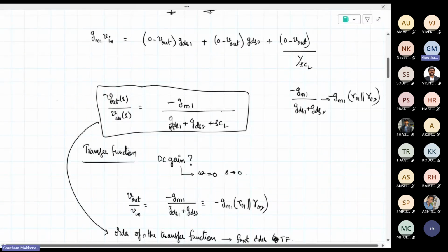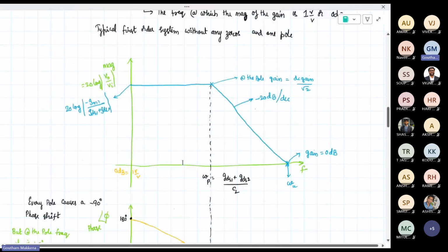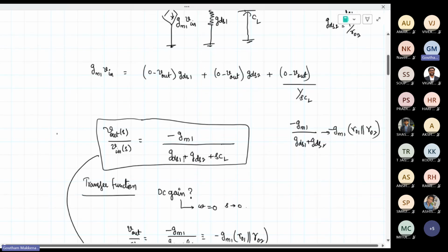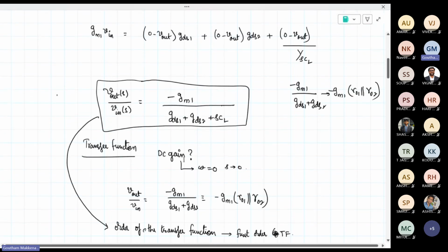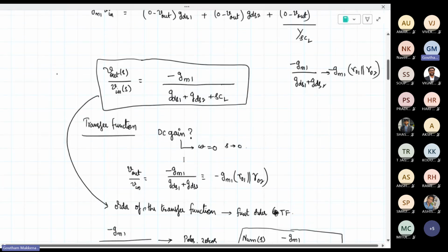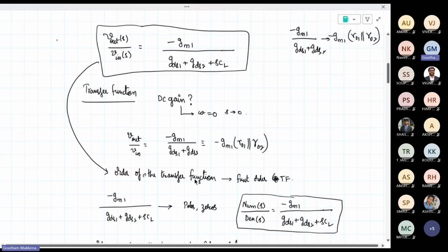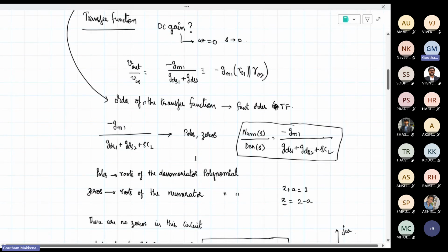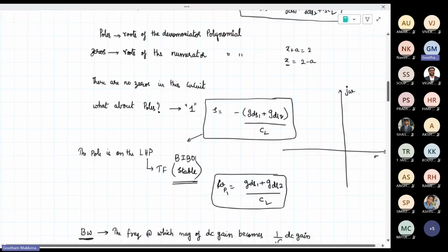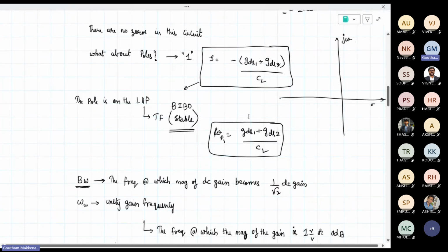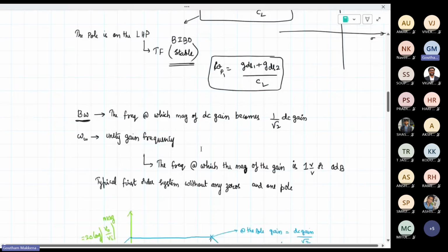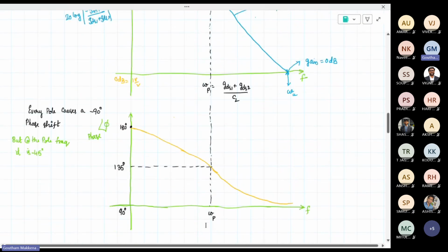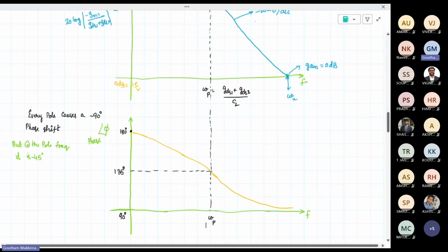What happened? We basically derived the transfer function again. We had to derive that in the previous class itself. Of course, today it would have made much more sense because we had the same discussion. The numerator polynomial, denominator polynomial, whatever we discussed today, the same thing, and the pole frequency. All those things we were having the discussion on, and the Bode magnitude plot, Bode phase plot.